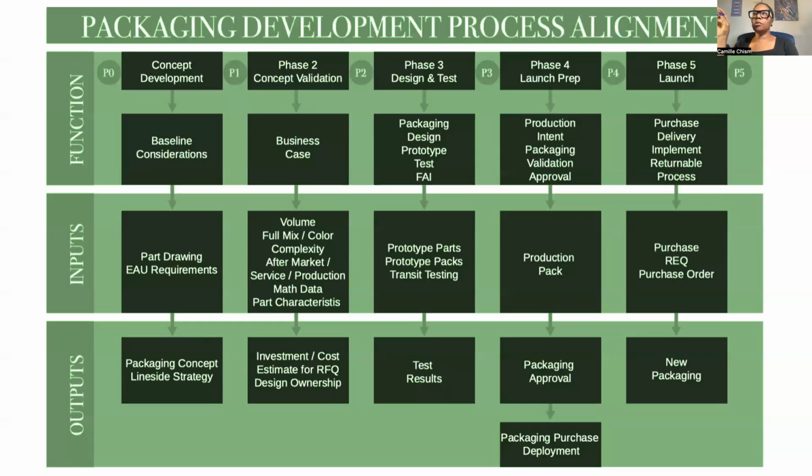The parts are going to be very, very close to production, if not production. And then you will take your packaging, which is more defined than a prototype, and it's mimicking the production as closely as possible. Say for some reason you can't get the production yet because you need higher quantities. This might be where you get a prototype mold, prototype tooling, instead of a full-blown mold.